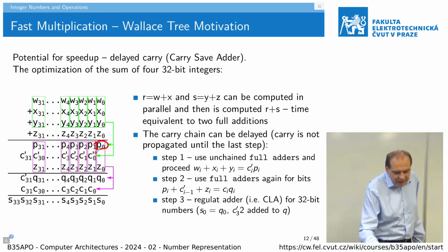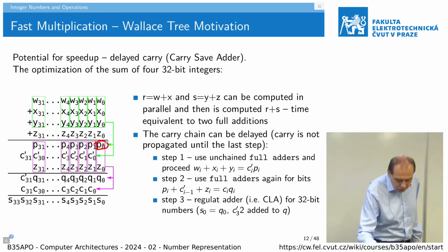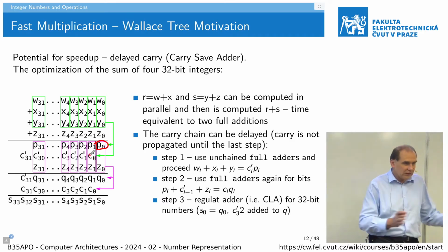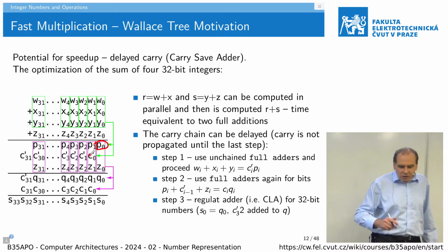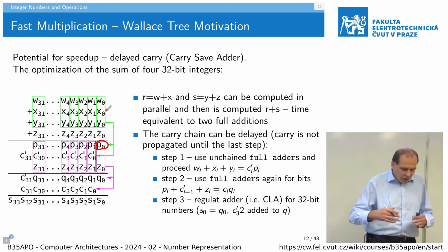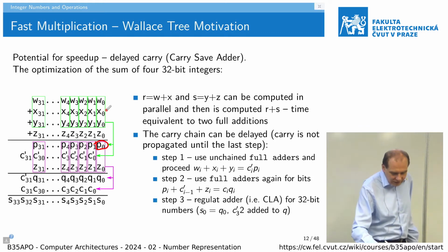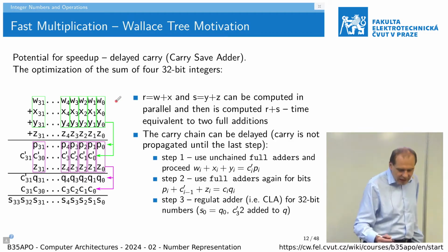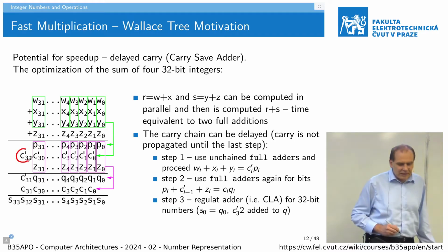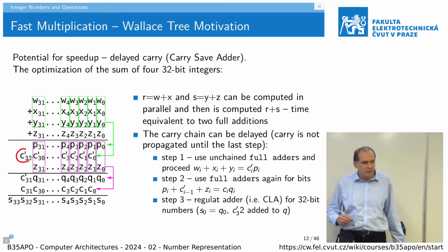And the carry goes from bit 0 and should be added to bit 1. So we have added, without the combination of the carry, only by simple parallel logic, those 3 numbers and get 2 numbers, where 1 is extended by the carry by 1 bit to the left.